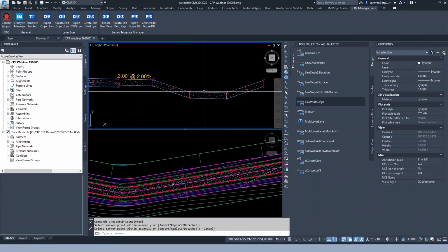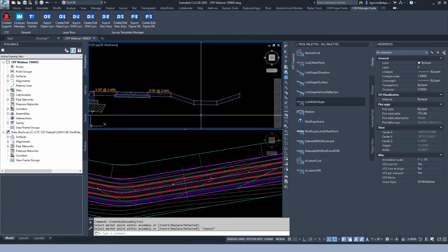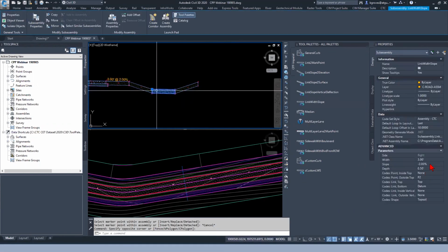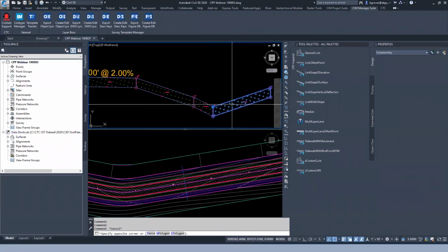And as many pieces of these that we choose to use is the complexity that we can achieve with our design. So there's obviously some best practices and some do's and don'ts and nuances of how the corridor toolset works, but you can have this kind of work however you want. You can have varying ditch side slopes by putting them in that way.